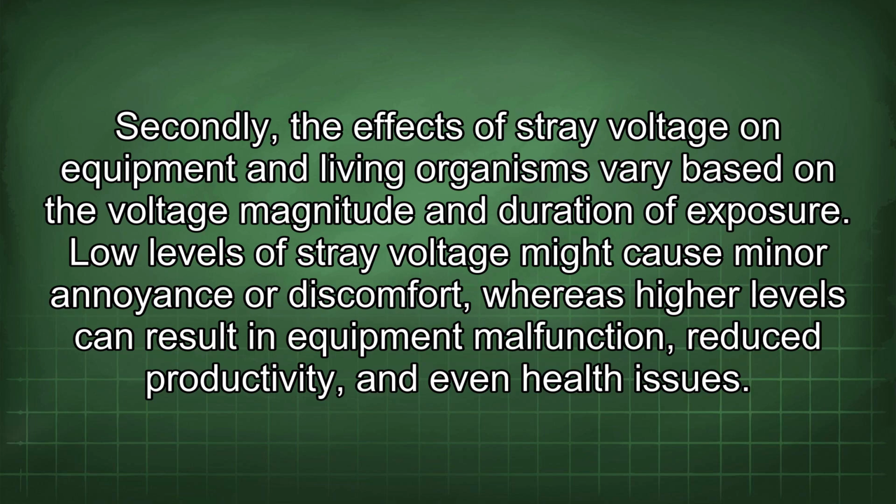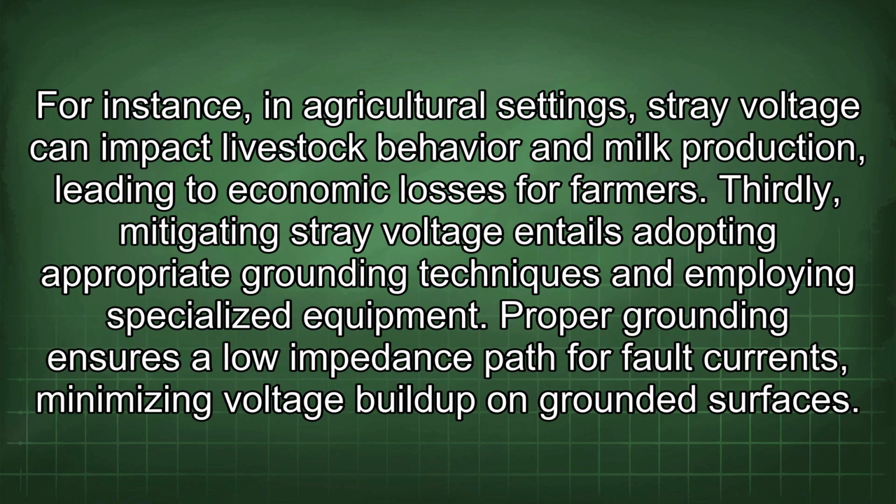Secondly, the effects of stray voltage on equipment and living organisms vary based on the voltage magnitude and duration of exposure. Low levels of stray voltage might cause minor annoyance or discomfort, whereas higher levels can result in equipment malfunction, reduced productivity, and even health issues. For instance, in agricultural settings, stray voltage can impact livestock behavior and milk production, leading to economic losses for farmers.